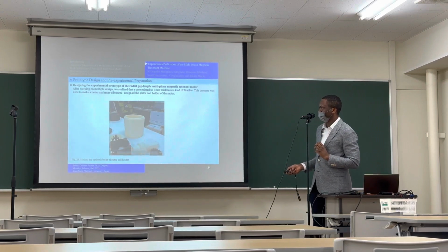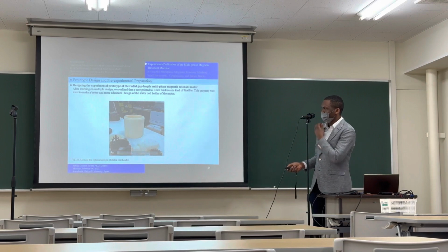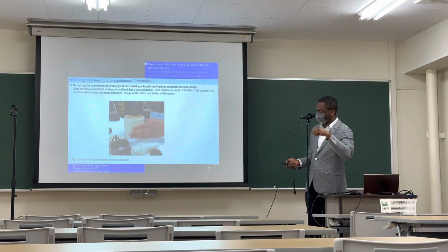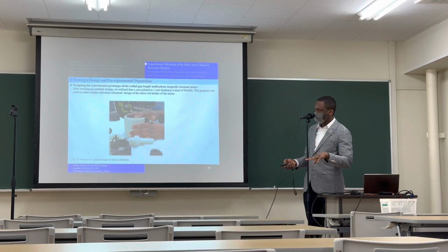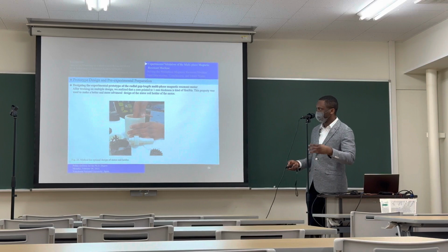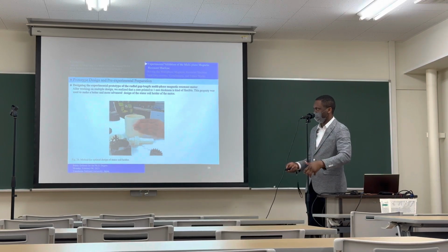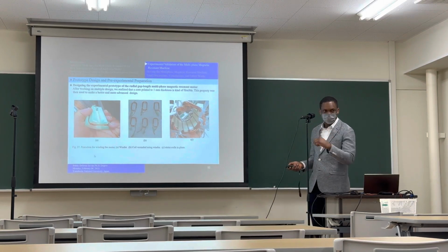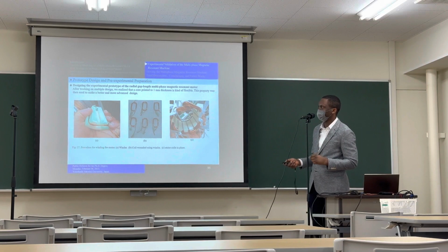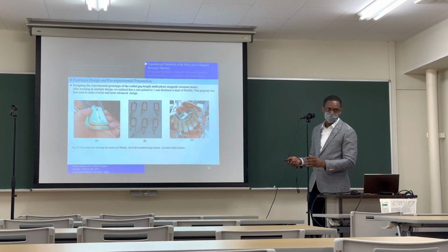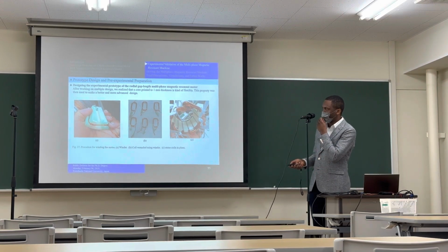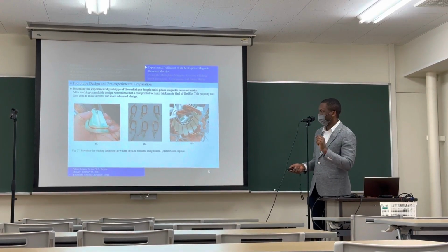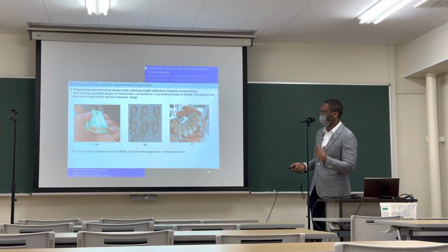With that stator coil holder, the idea is that when we have put the coil on the stator holder, we can then put it inside the main stator, just like a core, and it is removable. So you can remove it, easily wire it, and then put it back, just like that. The next stage is to wind it. To wind it, we first need to design a simple winder. With this winder, when you wind the coil, it creates the shape of the coil that has the same dimension as the machine itself.